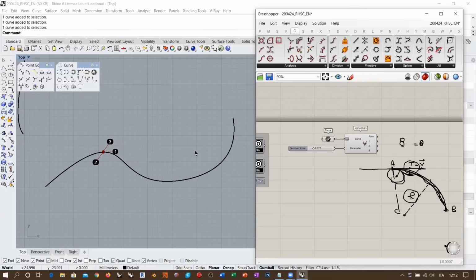But you also know that if the degree of a curve is 3, you cannot have a continuity level higher than, for example, G2, because G3 is already constant. So it's absolutely nonsensical, right? If you have a degree 5 curve, it is smoother, and you can also tweak the continuity of that curve to a higher level, which can be G3 and G4. So it's a complex set of information that you must take care of at the same time when you are drawing something.